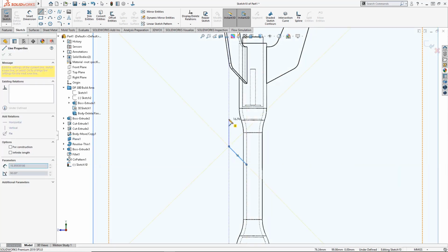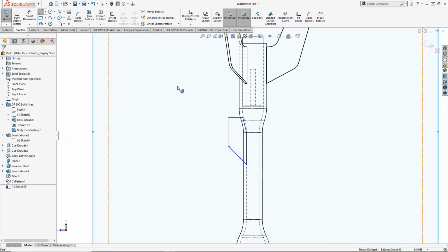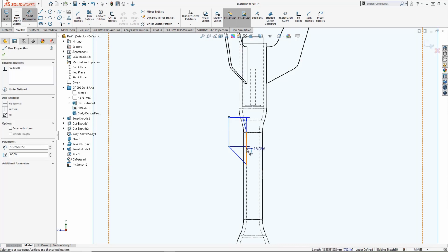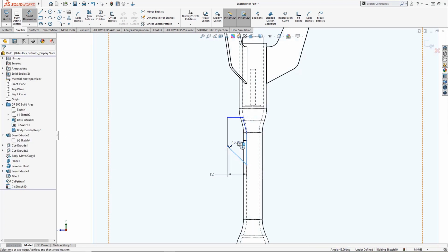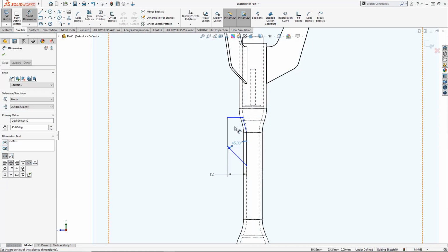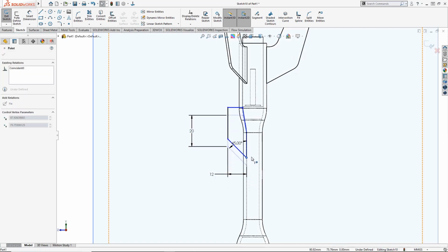Now I'm going to build this again in a similar way that I built my other things, like the fins, because what I'm going to ensure is that this file is going to work with minimal support when it comes to 3D printing. In this case, I'm actually going to go ahead and make sure that it's going to extend outside the 5-hour energy bottle, but by putting a 45-degree angle on this front, that face won't need any type of support material on the printer.